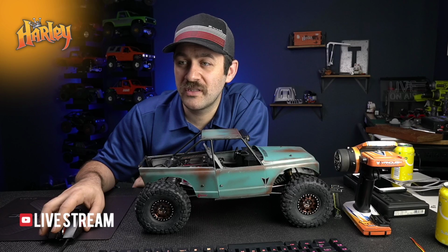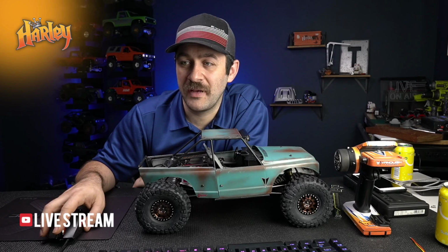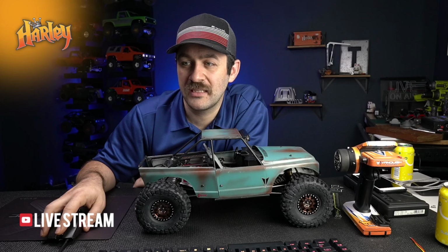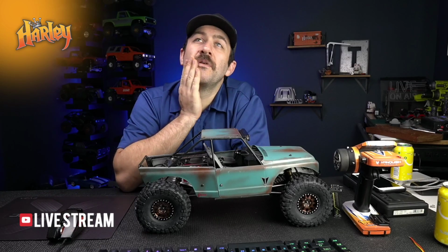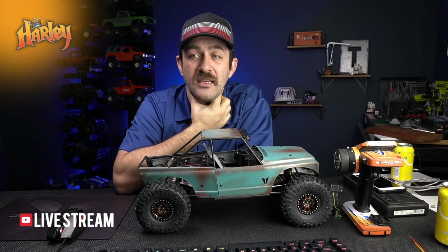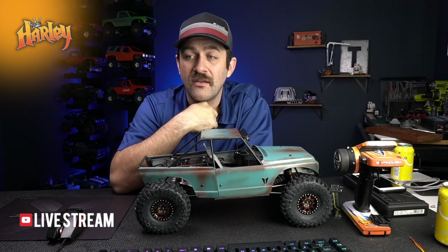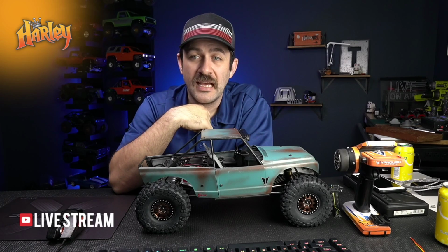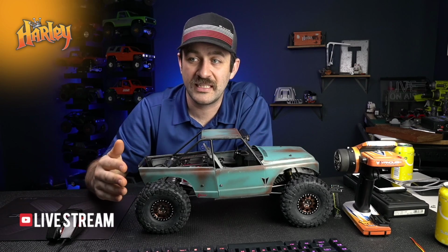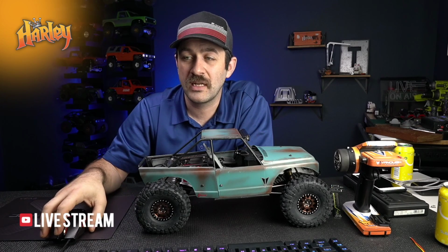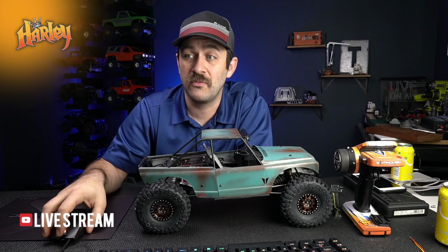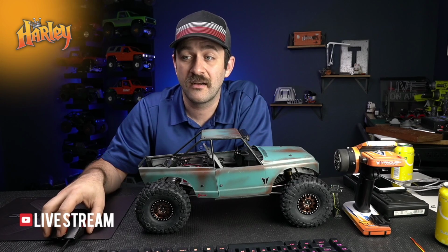What would be the most suitable gauge of sheet metal for body panels? .040 or less? Planning on building a Woods Runner chassis with custom-made CJ3A body. .040 would be way thick. I think you would be best off at like .025 or less, depending on aluminum or steel. .040 is thick. You'll want to be significantly thinner.